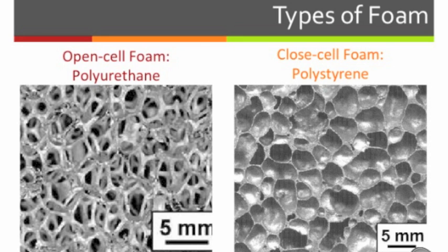There are two different types of foam, open cell and closed cell, which simply means the cells that form foams are either broken or closed. Differences between those types are density and firmness. Density measures the ability to support. Firmness measures the softness. Firmness is independent from density, which means it is possible to have a higher density foam that is soft.